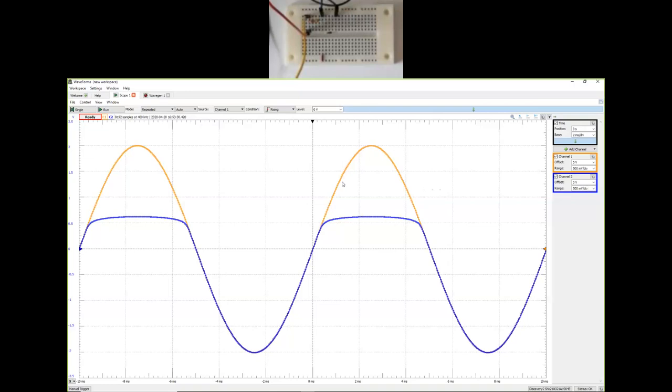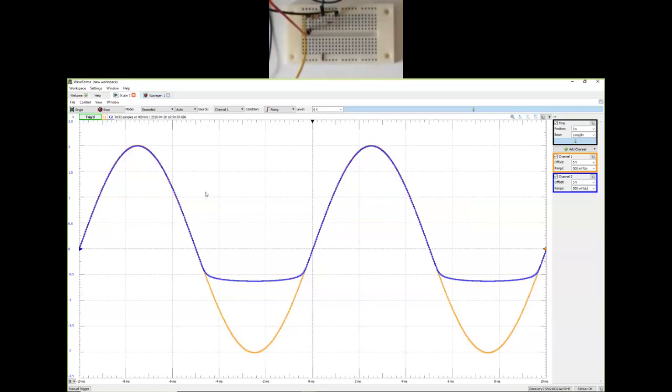On the positive side, it will essentially follow the input signal. So let us stop wavegen, temporarily take out the diode, flip it, put it back in, and run wavegen, run scope, and clearly you can see that this essentially flipped everything. So now the limiting is happening at negative 0.7, while on the positive side it follows the input signal.